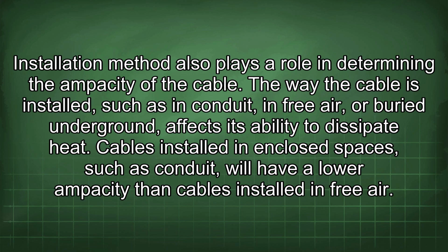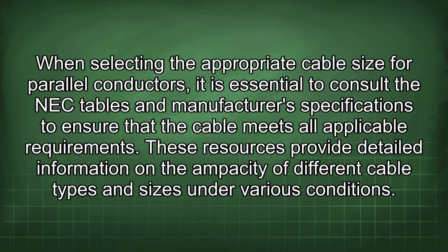Cables installed in enclosed spaces, such as conduit, will have a lower ampacity than cables installed in free air. When selecting the appropriate cable size for parallel conductors, it is essential to consult the NEC tables and manufacturer's specifications to ensure that the cable meets all applicable requirements. These resources provide detailed information on the ampacity of different cable types and sizes under various conditions.